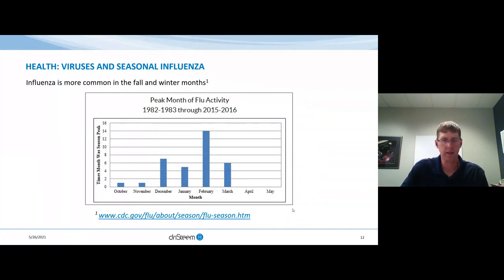So thinking about it, the CDC tracks flu outbreaks as an example. And flu season we think of as late fall and winter. And that's mainly because relative humidity drops during those temperatures. As I said, you've got colder temperatures, you're not able to have as much moisture outdoors. You bring it inside to the space, further drying it out because we're in heating mode. And so that's further reducing the relative humidity. And so there tends to be a trend of a low relative humidity, and 14 to 16 days later, you're looking at a potential flu outbreak as a result of it.